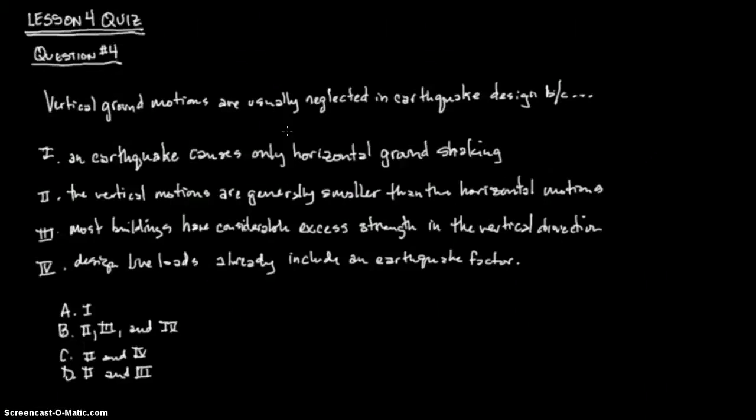You're going to have to repair especially your siding. If you have stucco, it's going to crack, or the brick's going to be cracked. So you're going to have to replace a lot of fascia type systems. But for the most part, even your structural system might deflect. Something might come in and sag like that because this beam was overstressed and it went past its elastic limit.